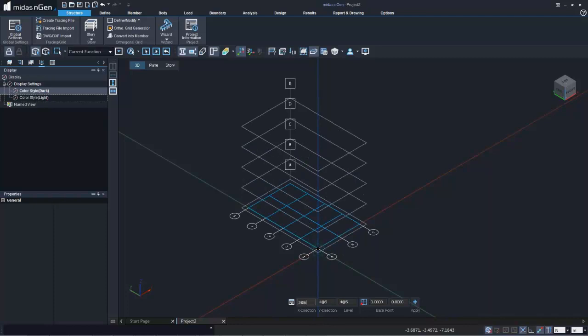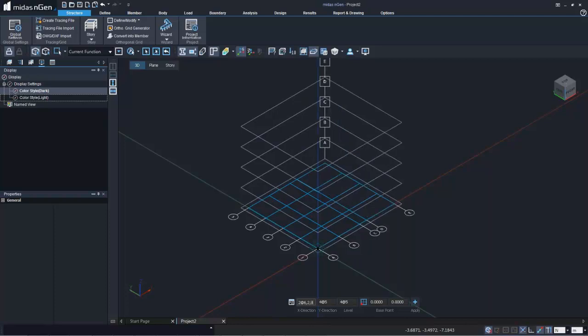So this is how you provide equal spacing 2 times. In case you have unequal spacing, you can simply provide a comma and write the next spacing, for example 2 meters, and then again a comma and then a distance of, let's say, 8 meters. In this way you can create spacings with unequal distances. All right, sir?